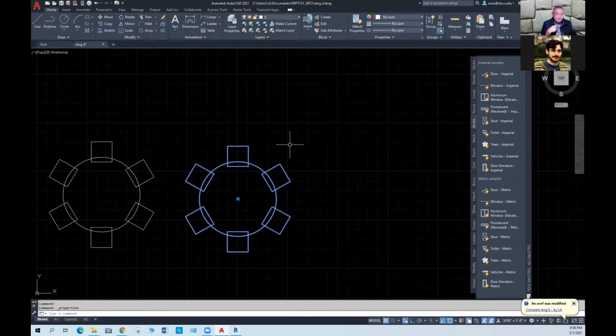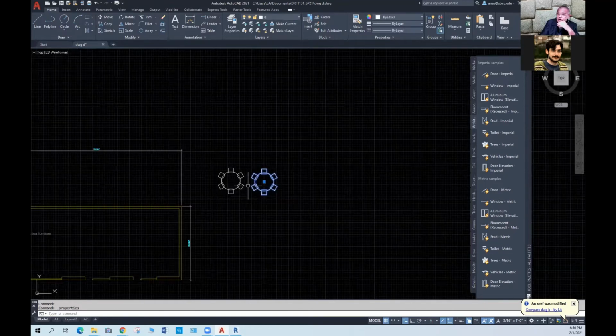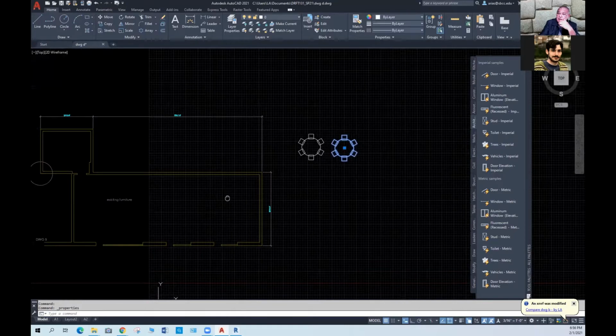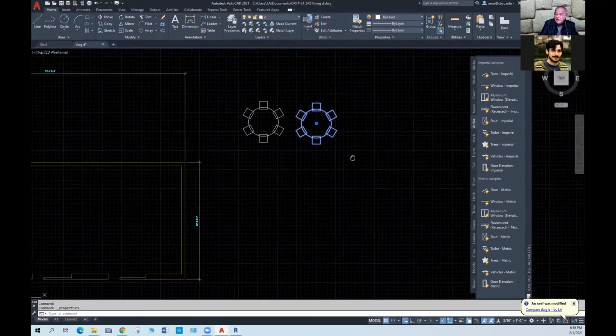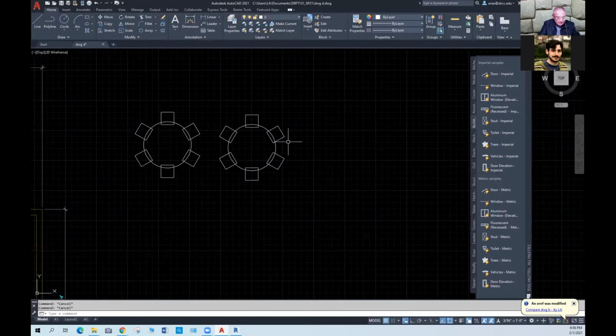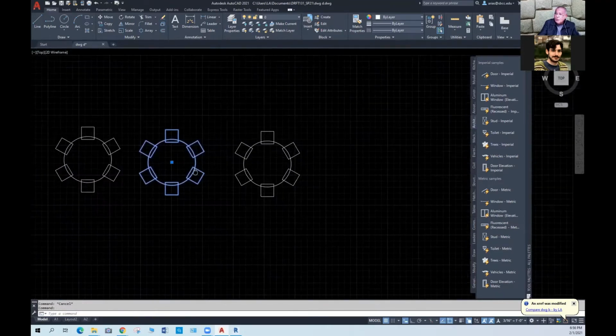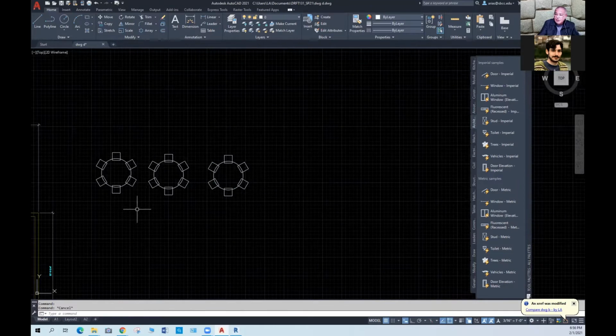When creating copy to clipboard or not, you can just leave the block like that if you don't mind that the name of the block is different. And so in this particular case, when you're creating a layout for a building like this, there will be some objects here that you can make blocks and then just copy them. The advantage of having a block is this. I'm going to copy this block here. And if I modify one, all of the objects that make up the block will modify.